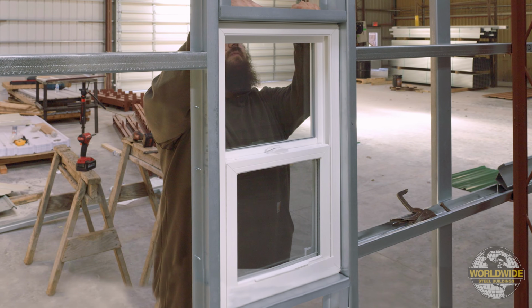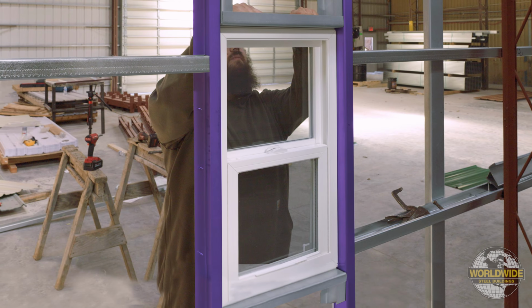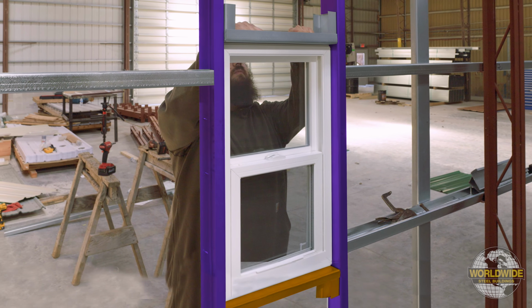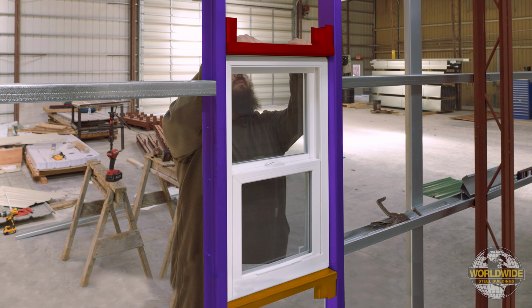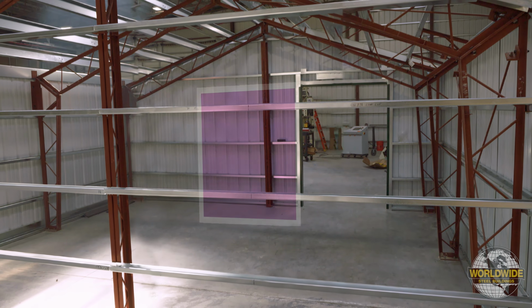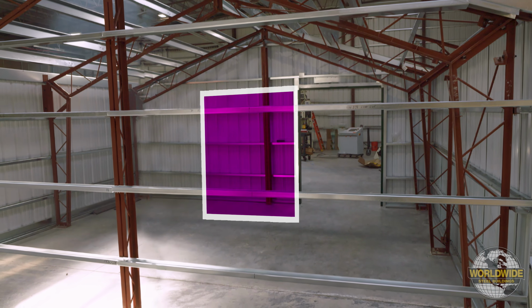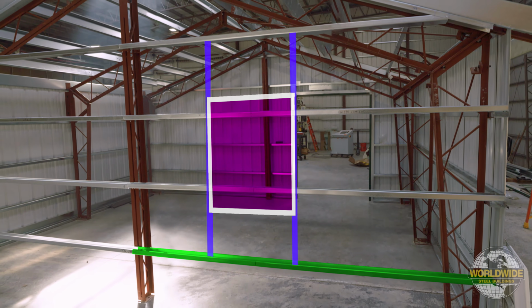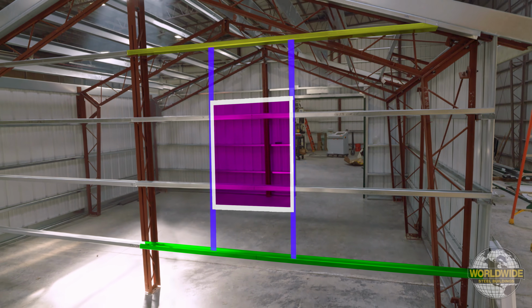When framing a window, you will have vertical jambs on each side of the window, a sill at the bottom of the window, and a header at the top of the window. Identify the location on your building where you want the window to be installed. The jambs will attach to the first girt below the windowsill and the first girt above the window header.